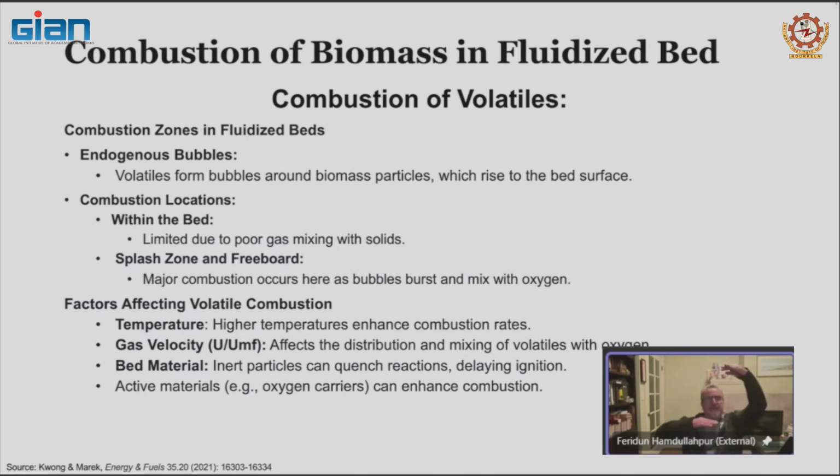That means you have the dense bed, the freeboard, then you make sure that you have proper heat transfer surfaces in the freeboard to capture the heat that is released from the combustion of volatile matter, okay? With char, it's a different story. So what are the factors affecting volatile combustion? Temperature.